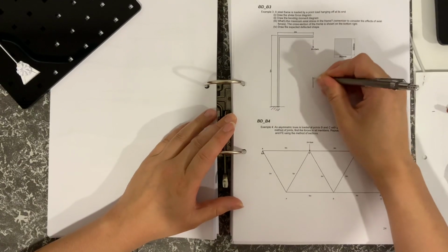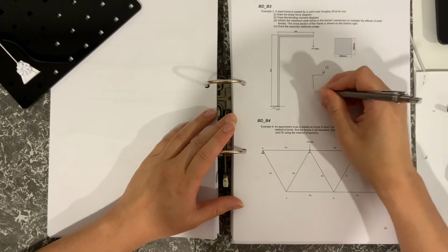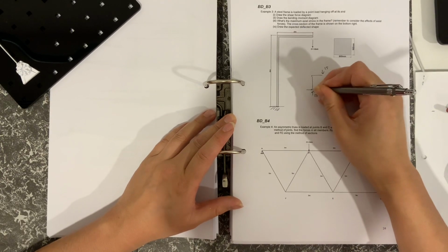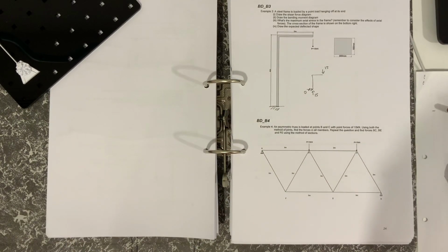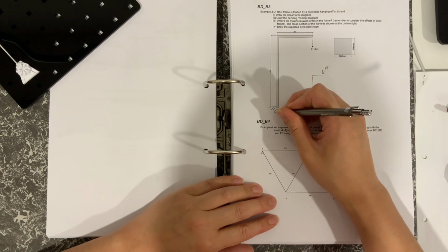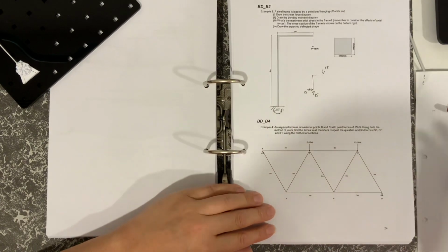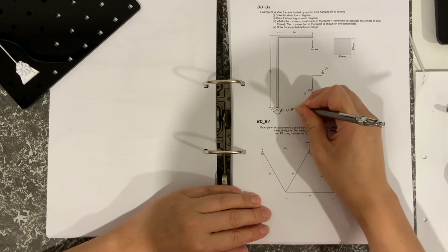So we'll have that, and then we'll have the 15, and then up here there would also be a 15, and then the horizontal force would be 0. So there wouldn't be any force there. And as you can see, it needs an anti-clockwise moment. So this is the reaction moment that I'm drawing, and the reaction moment must be 30 kilonewton meters.